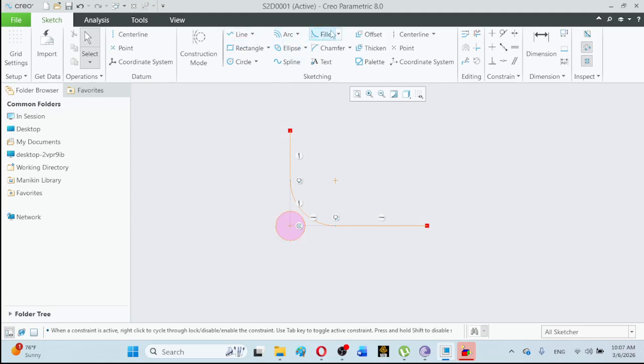But in the case of this other type, that is circular trim, as the name indicates, in the circular trim type, these original traces of the fillet lines will not be existing. Actually, the length of these traces is equal to the radius of this fillet. So these are actually defining the radius of the fillet. So the radius of the fillet can also be defined like this. For example, another way, I can draw a corner rectangle here like this.